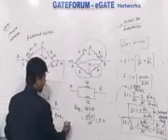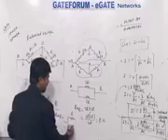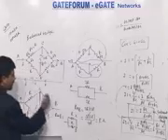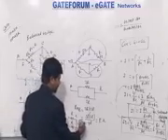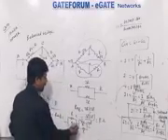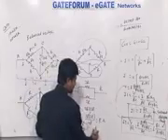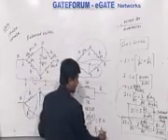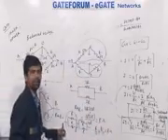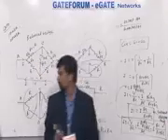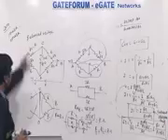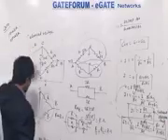So the equivalent structure you can draw as R parallel with R in between C point and D point, R parallel with R. R parallel with R is nothing but R by 2, half of this resistance, plus R parallel with R is R by 2, which is equal to R ohm. So in that way you can find out the equivalent resistance between point A and point B by using series parallel combination of the resistance.